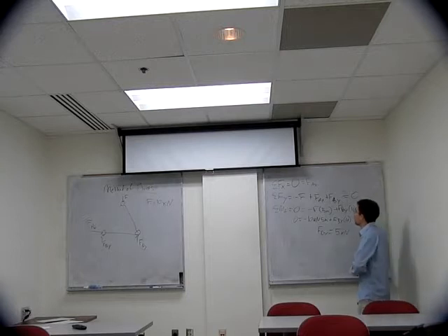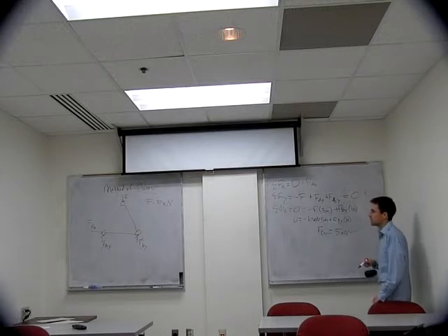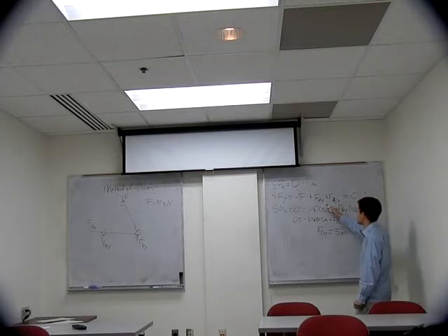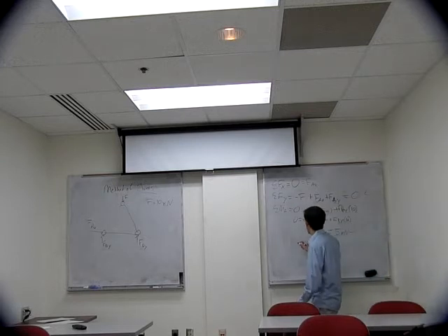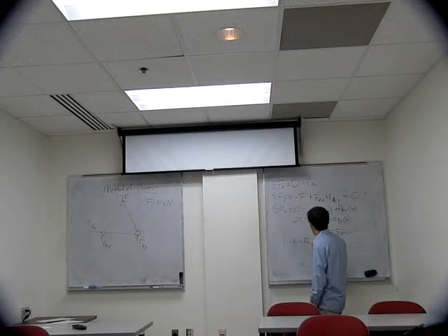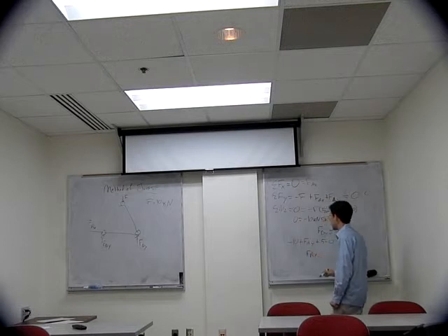All right. So now we can use this solution, plug it back into the summation of our forces in the y direction to solve for our reaction force at A in the y direction. So we have negative 10 plus FAY plus 5 is equal to 0. So our reaction force at A will also be equal to 5.